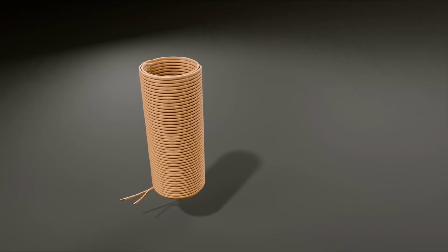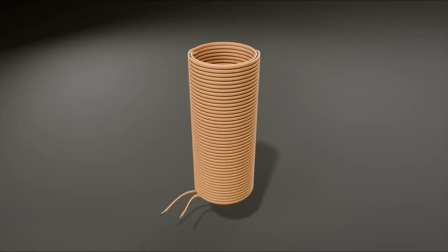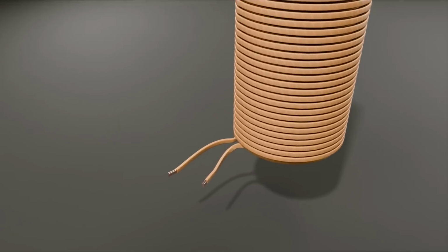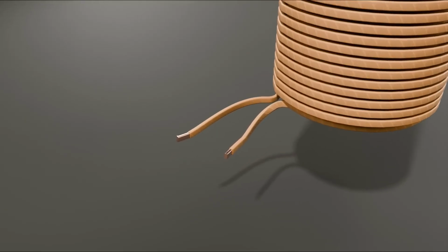Helical winding is mostly used for low-voltage windings in power transformers. It's the simplest type of winding and is ideal for low-voltage, high-current applications. In a helical winding, the conductor is shaped in the form of a helix. The amount of current in the LV winding of a power transformer can be thousands of amperes, which is why a very thick conductor is used for the LV winding.